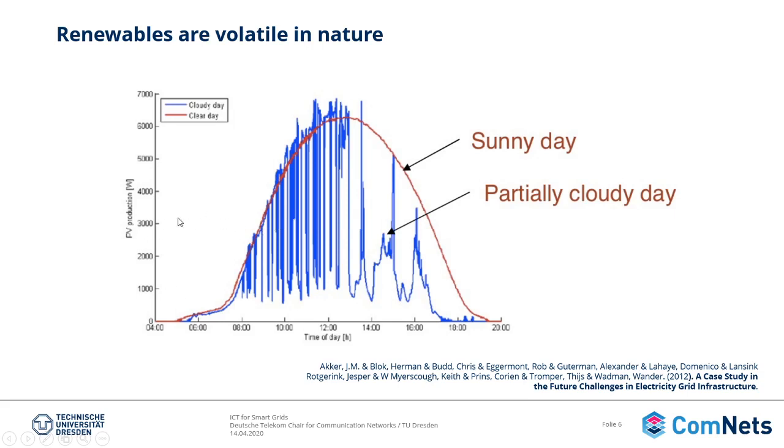However, if you do have battery systems on site at home, you can use the times when your power demand is lower than your generated power. Since you're not going to do anything with this and you cannot sell it back to the grid, you can store this excess power into batteries and wait until your power demand is higher than the power generated, and you can use it to push up this red curve up to here. And in that case, you are completely self-sufficient.